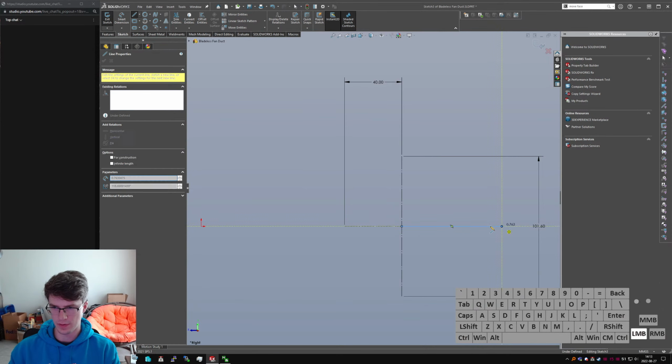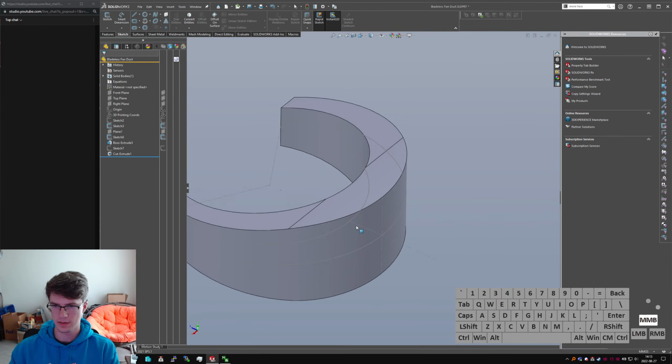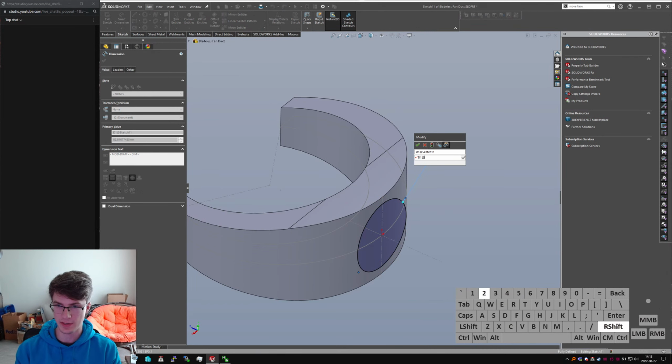I'm going to say I want in this sketch built in the length of my mounting boss. So now, when I come back to plane 1 and say extruded boss, I draw my circle of whatever size. In fact, I'll make it an equation so that it breaks. I can tell when the reference breaks later. Sketch 3.